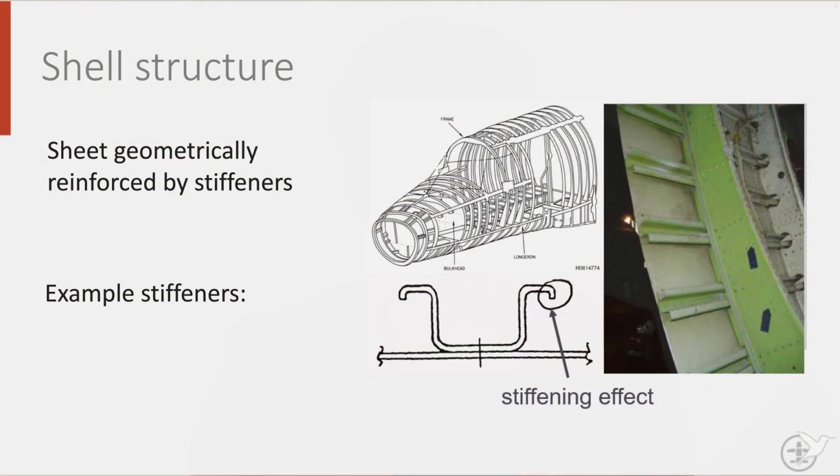Now let us take a look at the fuselage. A fuselage has three types of stiffeners to keep its shape and carry the load. Stringers, such as the ones in wings, longerons, heavy longitudinal stiffeners effectively combining several stringers, and frames to maintain the circumferential shape. In the photo here you can see inverted hat stringers. Using them this way, they are more inspectable. The curve at the rim of the hat is added to give more stiffness.